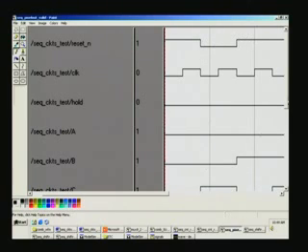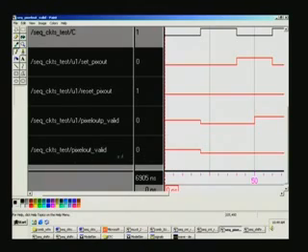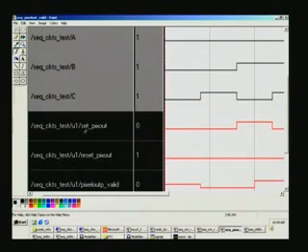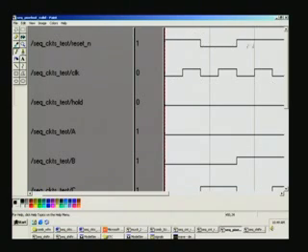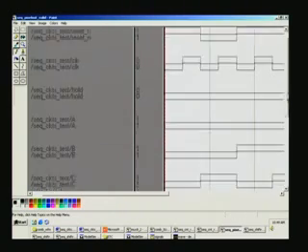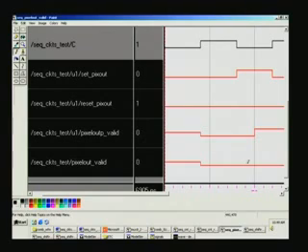Only at that point of time, the two registers, pixel out P, that's the first register we saw, and pixel out valid, the actual desired one, are affected. So something is happening here. We'll see what is happening, and we have also seen this will be set at a particular point of time for some condition of ABC, and reset at another point of time. And before that, let us see what happens at a reset point when it goes low. What you need to do is reset all the outputs. So that's what is happening here in this condition.